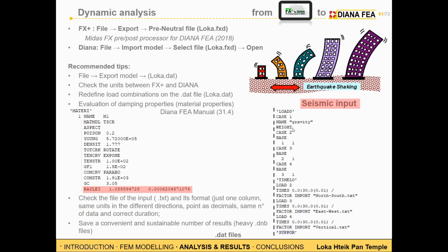And then we can talk about the base excitation load. Base excitation is the option we have found before in the graphical interface to apply dynamic inputs to the structure. The first number, the first string, refers to the load we want to apply, such as base excitation.